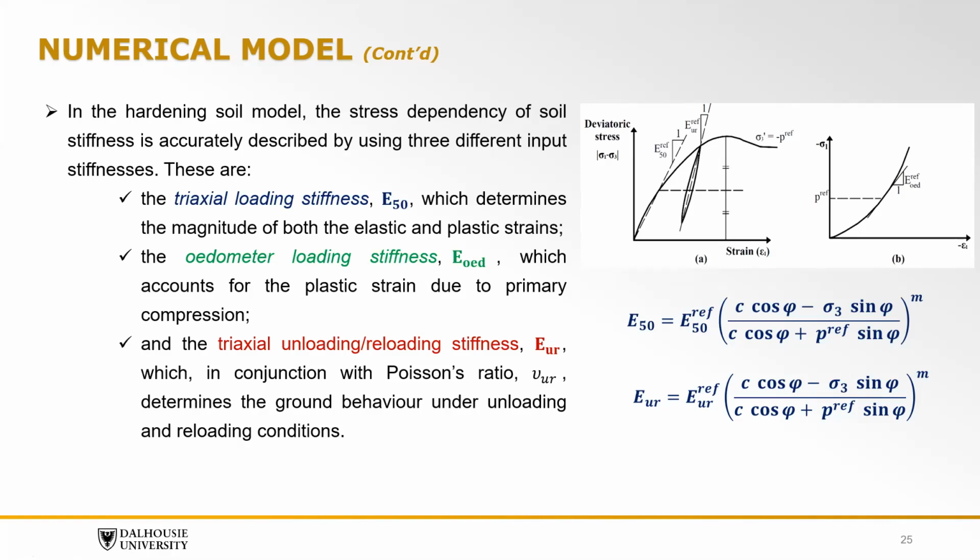So basically, this soil model is comprehensive in terms of the nature of the loading itself and the soil that will be loaded. So we know that the stiffness of the soil during loading is different than its stiffness during unloading. Constrained stiffness is different than the stiffness in triaxial. So this soil model here is capable of addressing all of this.